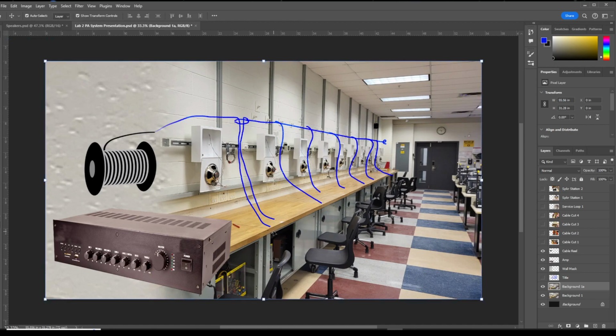Why are we cutting it and joining it together? What's the point? Well, we're joining it back together after we cut it so the line can continue. But we're also cutting this loop right here so we can tap in with another wire that we're going to run from that point through the back here, right into the speaker station, and we're going to connect that here. So again, don't shortchange yourself on the wire.